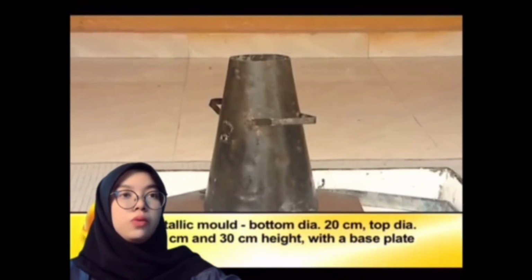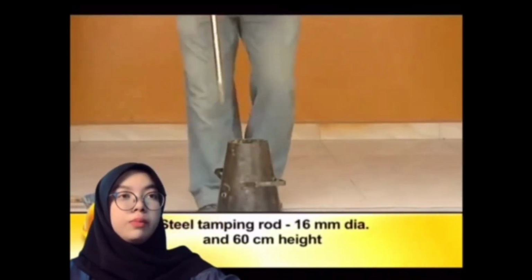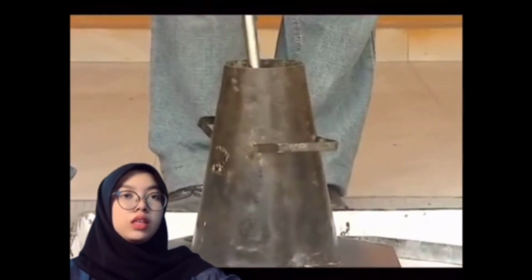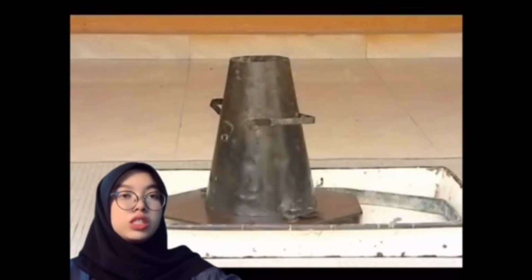The apparatus for conducting the slump test essentially consists of a metallic mold in the form of a frustum of a cone with a base plate. A steel tamping rod of 16 mm diameter and 60 cm length is to be used for compacting. The internal surface of the mold should be thoroughly cleaned of moisture and any hardened concrete before commencing the test.